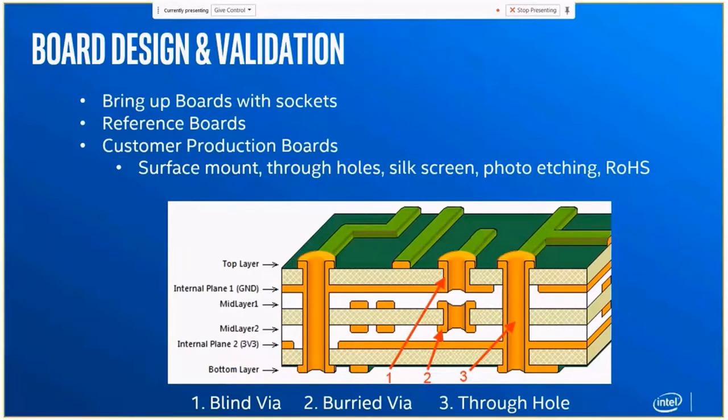And finally, you have this RoHS, that's reduction of hazardous substances, something like that. It's actually a standard. So for example, the boards should not contain any lead, right? Things like that, so you need to get RoHS certification. For any board that you design, if you're doing a reference board, maybe if you use lead, it works better, connectivity is better or something. But you can't give that as a reference board to a customer because they can't copy that design and use it, right? So you need to make sure it's RoHS compliant.